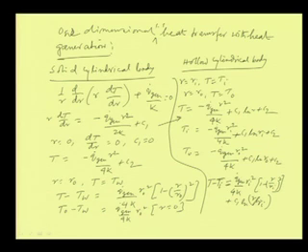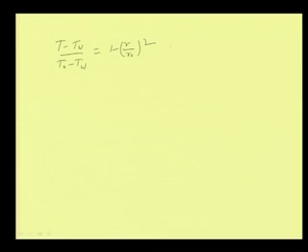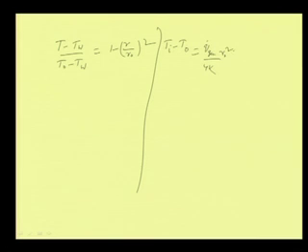And in exactly a similar way, we can write T_i minus T_0 also to find out the value of C_1. So, if I write here T_i minus T_0, then we will get Q_0 dot gen by 4k into R_o square into 1 minus (R_i by R_o) whole square plus C_1 ln(R_i by R_o).